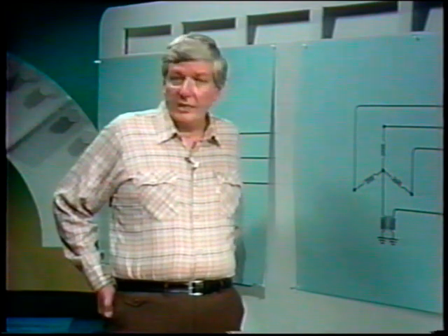This would induce a voltage in the secondary side of the transformer. The secondary side of the transformer is connected to instrumentation that detects current flow through the transformer. This instrumentation either initiates an alarm or indicates in some other way that there is current flow through the transformer. In some cases, it'll shut the generator down.